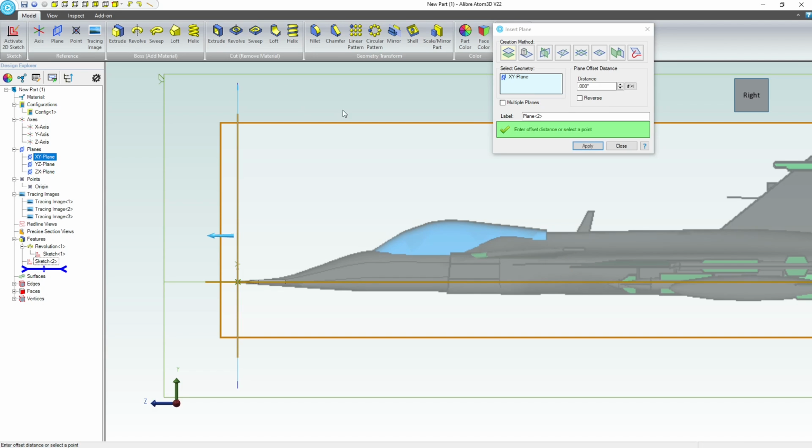So we'll add this as a plane and we'll choose an offset distance. And of course I'll reverse my offset. And with my normal to profile capability, I'll probably go right here. So we'll loft normal to the profile and up, and maybe normal to that profile as well. And we can kind of play with that as we go. What would the best geometry be?